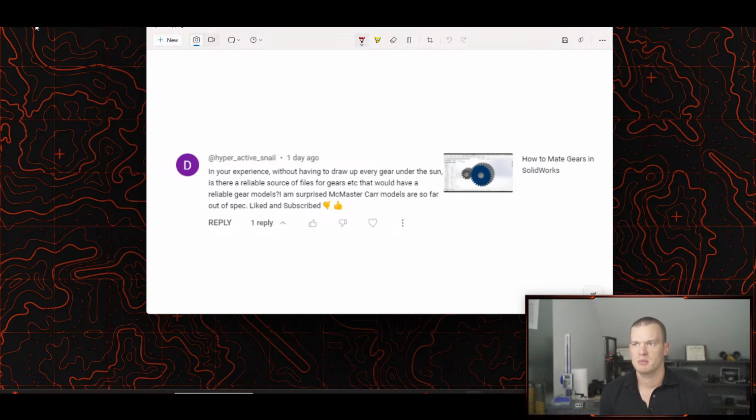And that caveat of does the model need to be correct brings up my first point in responding to this. Do you really need your geometry to be correct, right? It's like using a screw or some other piece of hardware. Sometimes you can have a dummy piece of geometry in your model that just represents the screw, and you know what the spec is of that screw, and it can save you processing time, especially in big assemblies where you're not trying to process those threads, right? Because that's complex geometry and it takes time. And if you have a whole bunch of screws in your assembly, that can slow you down.